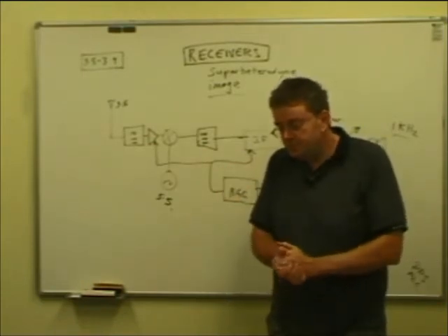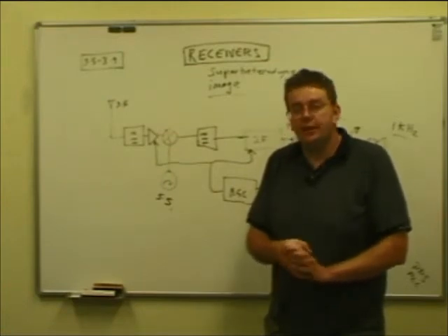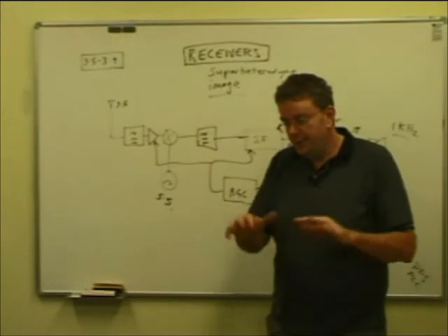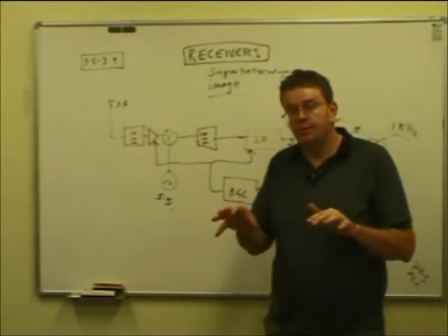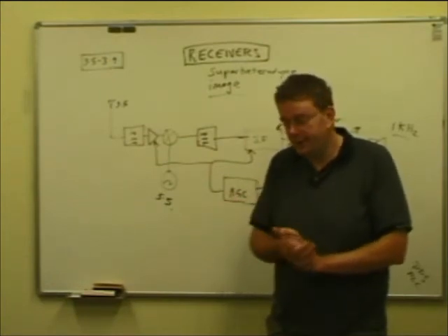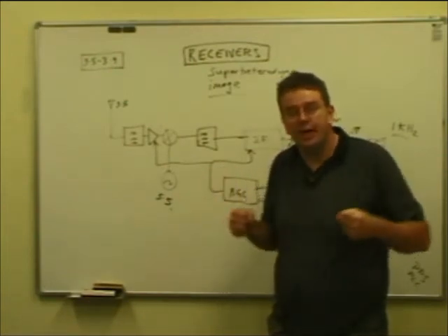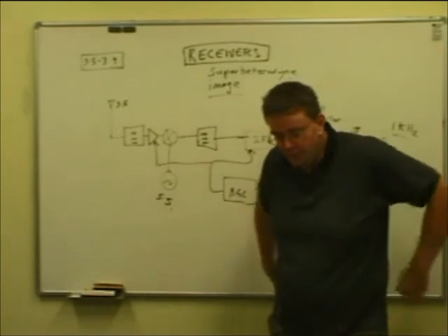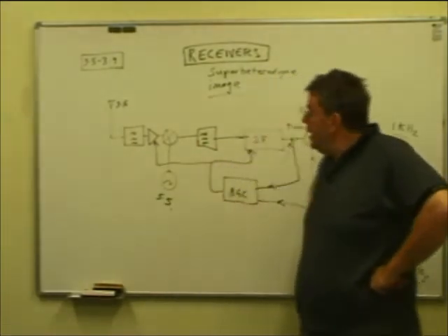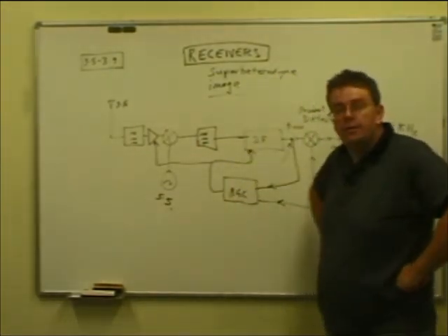And what single sideband systems will often do is have a bit of a delay in there, so that it will just keep things set as they were for a second or so, maybe just around the second mark, just so you don't get what's called pumping, big changes in the loudness coming out of your receiver with speech going on and off and so on. Right, so that's automatic gain control.